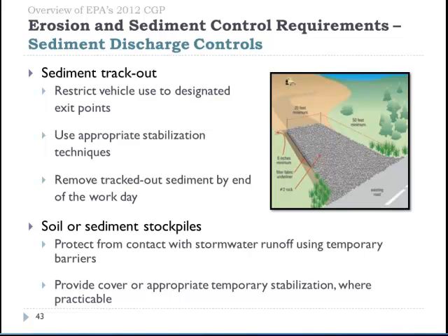trackout. Where trackout does occur, of course, these things aren't 100% foolproof, but where sediment trackout does occur, the requirement is to remove that sediment through whatever means, vacuuming or sweeping, by the end of the workday.